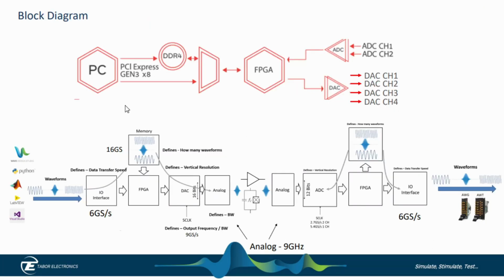So we've looked at this side of the block diagram, and we've especially focused on the DAC in the previous demonstration. We've shown how you can use multiple Nyquist zones to get to higher frequencies. We've also shown how you can use interpolation to move your Nyquist zones around if you wish. And then we also demonstrated the IQ modulator and how that can be used to create a fully modulated signal. Next, let's take a look at the digitizer side.